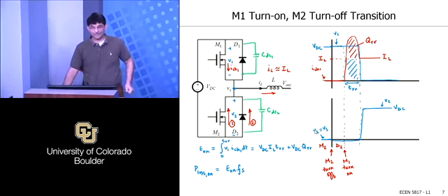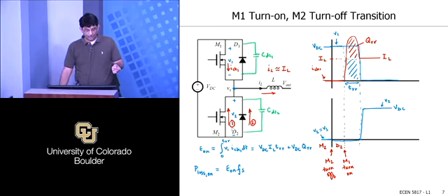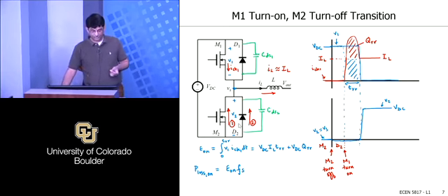It actually hurts, right? So first, think about it. In the beginning, when you started this transition, the current would shift from the MOSFET, let's say, to CDS2. What it does to CDS2 is discharge it more. As soon as the CDS voltage, the negative voltage, becomes enough to forward bias the diode, the diode turns on. So the CDS voltage isn't going to change anymore, and you're back to the situation where the diode is conducting. Not much changed really.